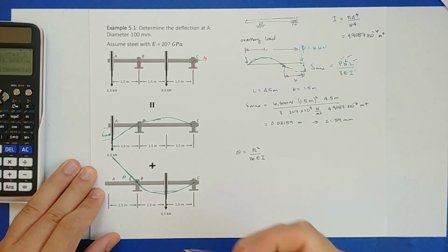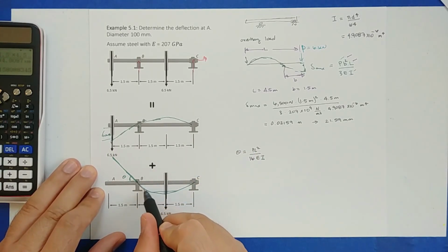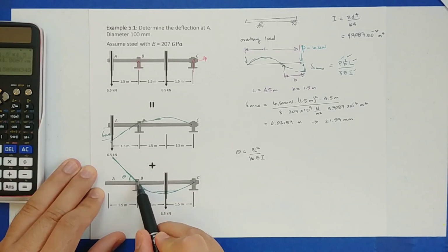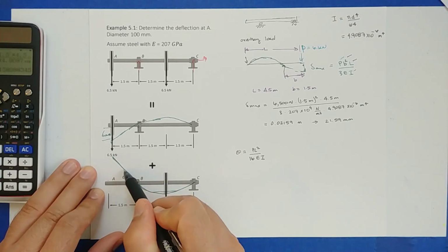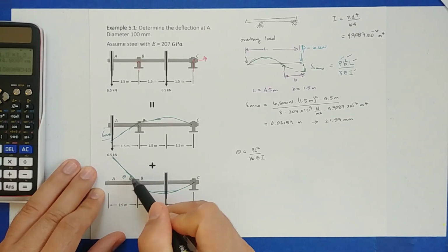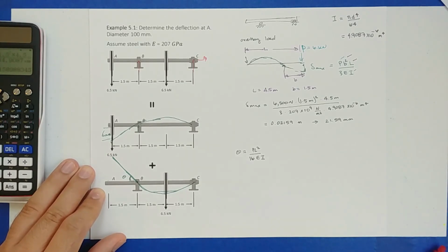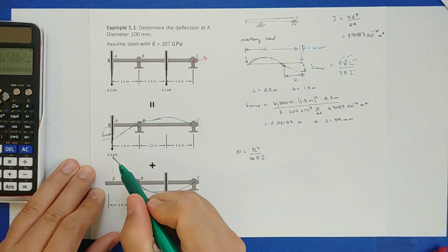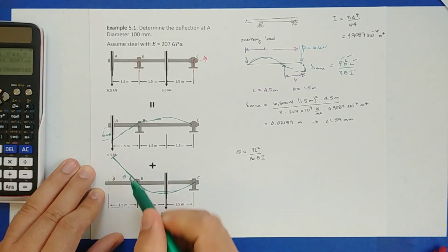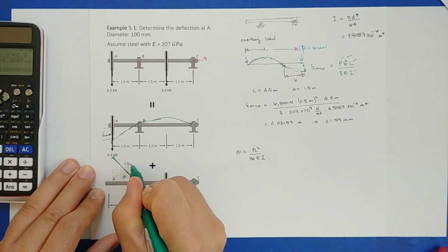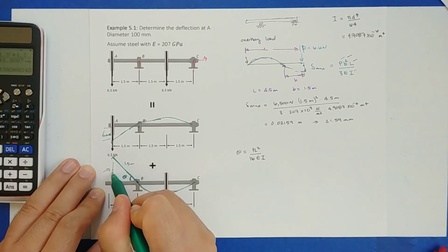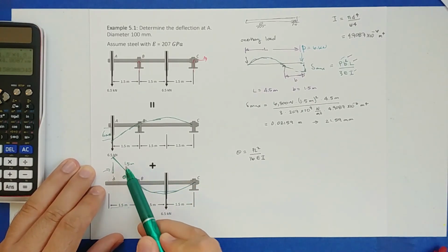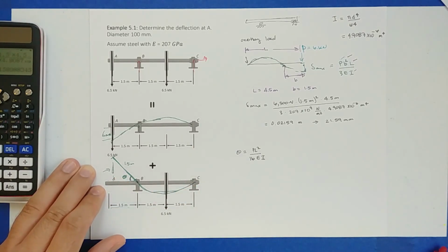And here's the logic: the beam is going to deflect like so. It has a curvature because there's a load here and then there are loads at the two ends from the reactions on this bearing. But afterwards, there's no loading, so the beam is not going to deform. It's just going to continue in a straight line with whatever slope we have over here. Well, we can use some trigonometry, right? Because this is 1.5, the original overhung length, and if we have this angle theta, we can use trigonometry to figure out this side, the side opposite to the angle theta. So first we'll calculate what this angle is.